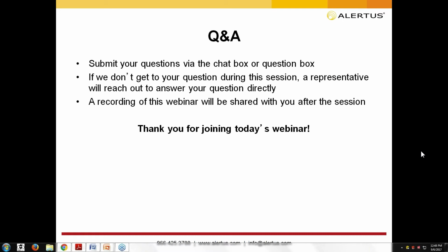Absolutely. The code, NFPA 72, Chapter 24, specifically says that as long as those speakers are not labeled for fire and they're only labeled for alarm or not labeled at all, they can be leveraged by a mass notification system.